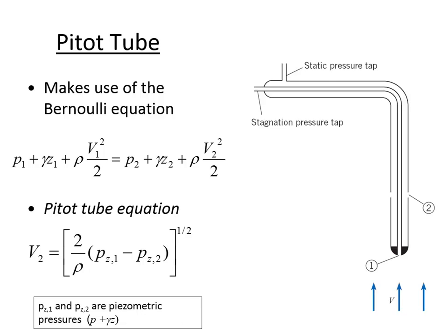When you first put that tube down, the water will go in a little bit, and that forces the water level up. Initially the water goes in, but then it stops because the weight of this water is acting downward, and that's equal to the pressure that increases at the opening of a stagnation tube. If you take into account the added pressure over the area of the opening of that stagnation tube, that is what accounts for the added weight of the water that's elevated above the free surface of the water.